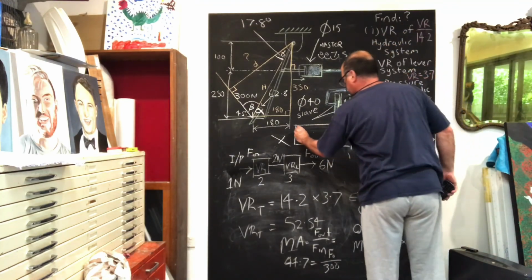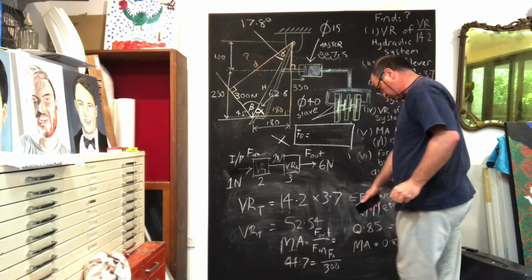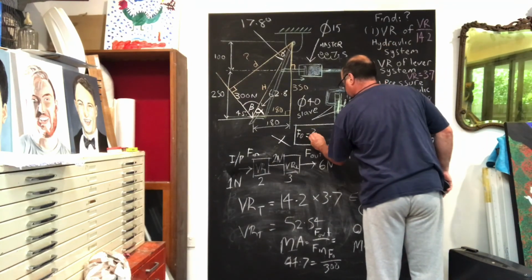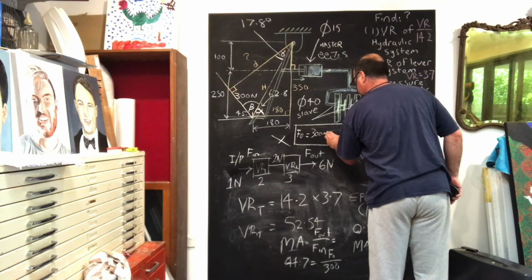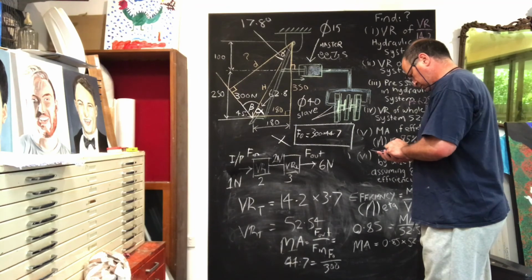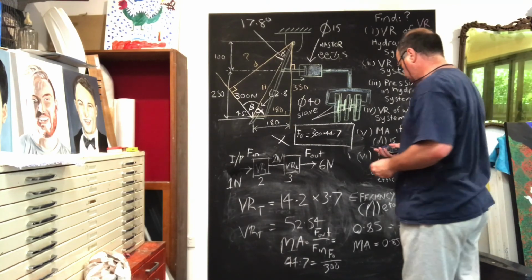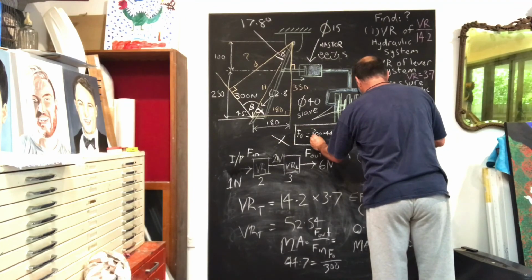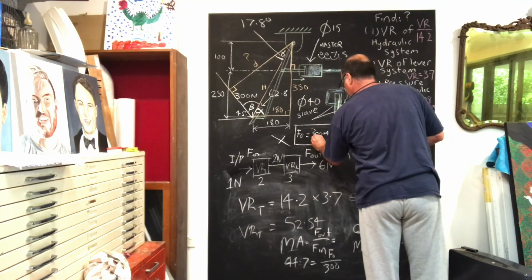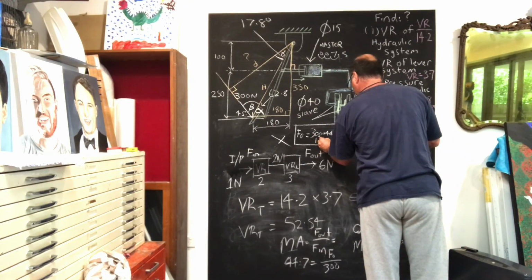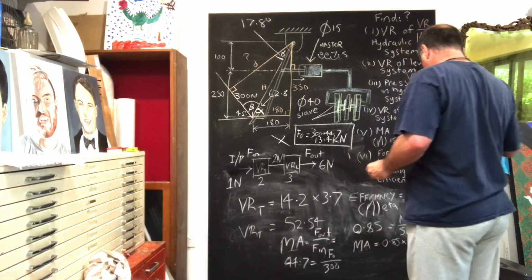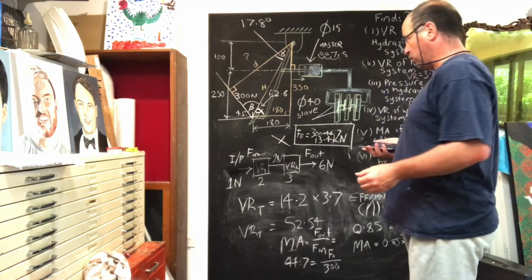So we're going to go force out is going to be equal to, we're changing the subject of this equation down here. We're going to make it 300 by 44.7. And we end up with 13,410 newtons, and we're going to convert that to kilonewtons by dividing by 1,000, so it's 13.4 kilonewtons. And that is the whole of the question done.